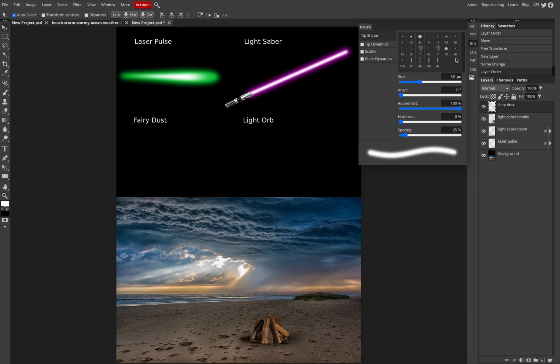So if I look at the different options available, I'm going to click on the 24 in the top right side. It's a softer edge where you can see that it's very strong in the middle, and then on the edge it kind of fades away. With this 24 selected, I can modify the size of the brush at any point, but I want to show you how we can modify and create a more custom brush using the different options in this brush panel.